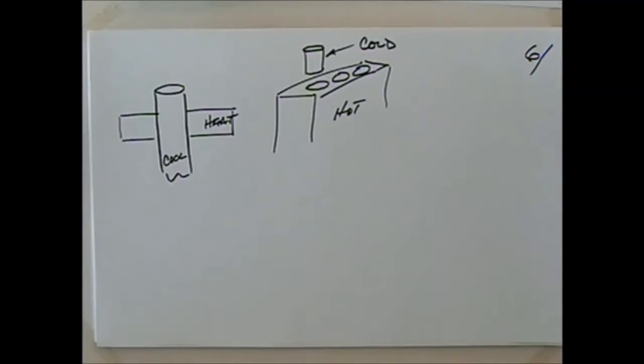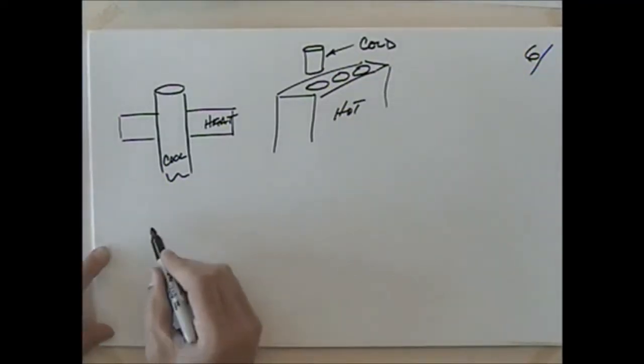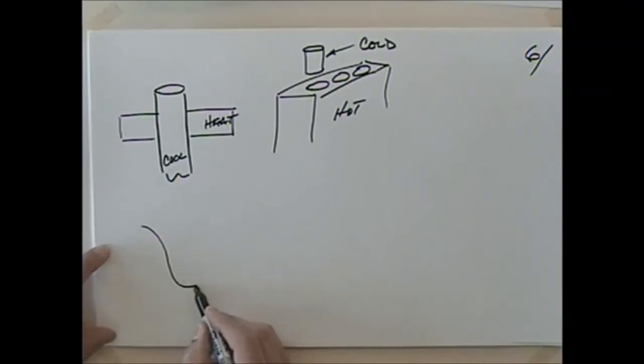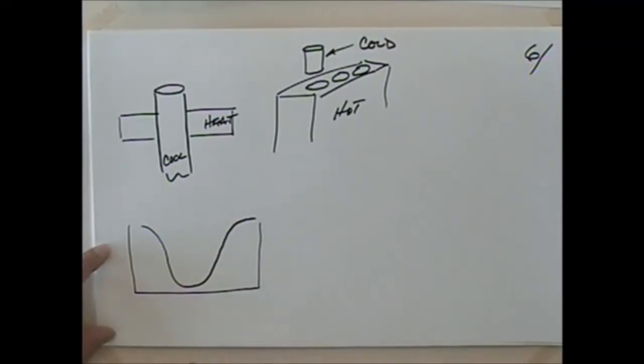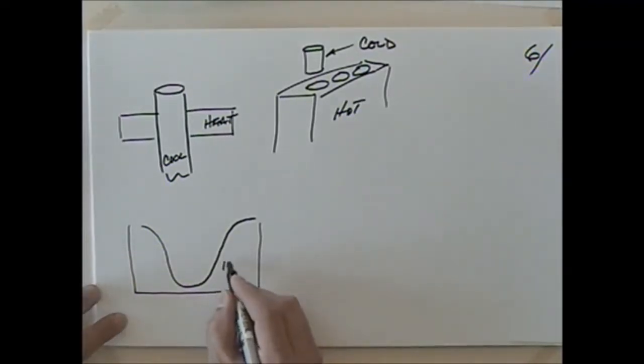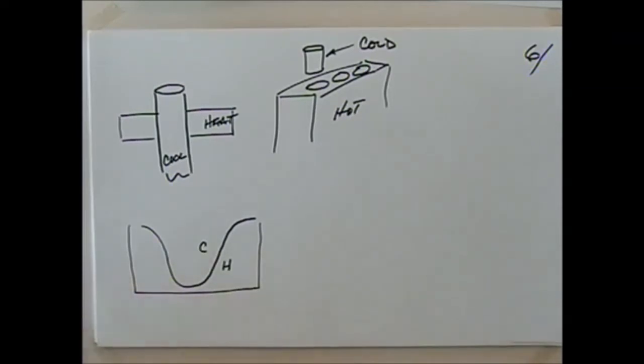So it's hard to say exactly when it was cast, but cast in 1752 and 1753. It has residual tensile stresses in the outside surface because the casting cooled more rapidly from the inside. I don't know if we have any people that specialize in making bells in here, but if you're going to cast a bell, you usually cast the bells upside down. So you'll build a form like this and cast the bell upside down. So this is going to remain quite a bit hotter in here, and this is going to cool down quicker like that. Okay. So it has residual tensile stresses in the outside surface because the casting cooled most rapidly from the inside surface. The principle is that what cools last is in residual tension. Okay, so you've got tension on the outside surface.